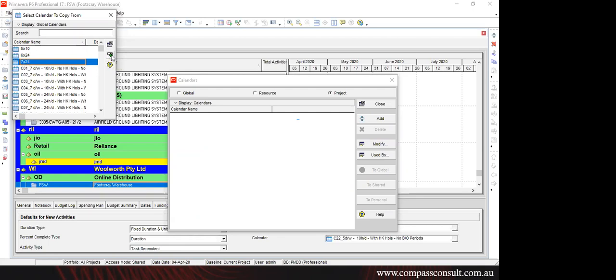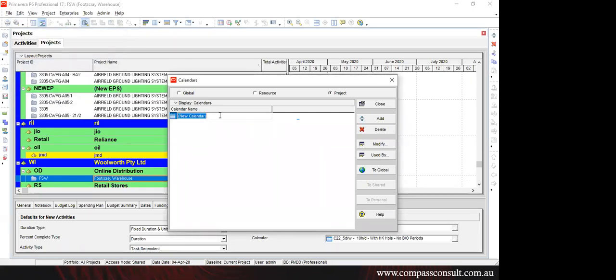So what's the benefit of that? We can customize the detailing of timing very easily. So I'm taking 6 days and 10 hours. Basically it's a pattern for giving the name of the calendar. Primavera is a multi-user software, so people are using it with different roles. Some have rights to manage project creation and calendars, and others have rights to add WBS and activities only. That's why we have to give a proper name to the calendar so anyone can identify it properly. So we're putting 6 days and 10 hours.